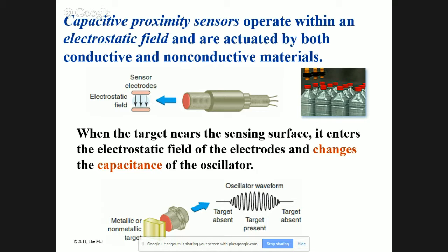Typically you see them on air cylinders. On the backside of an air cylinder or hydraulic cylinder, there will be a magnet inside, and the little sensor is adjustable up and down the entire length of the cylinder. When it sees the magnet inside, it tells that the cylinder is either closed or open, yes.